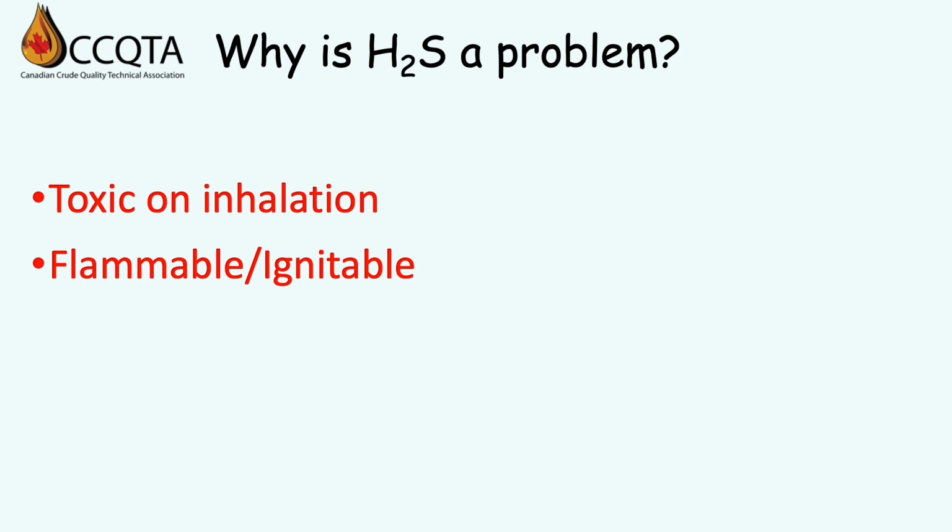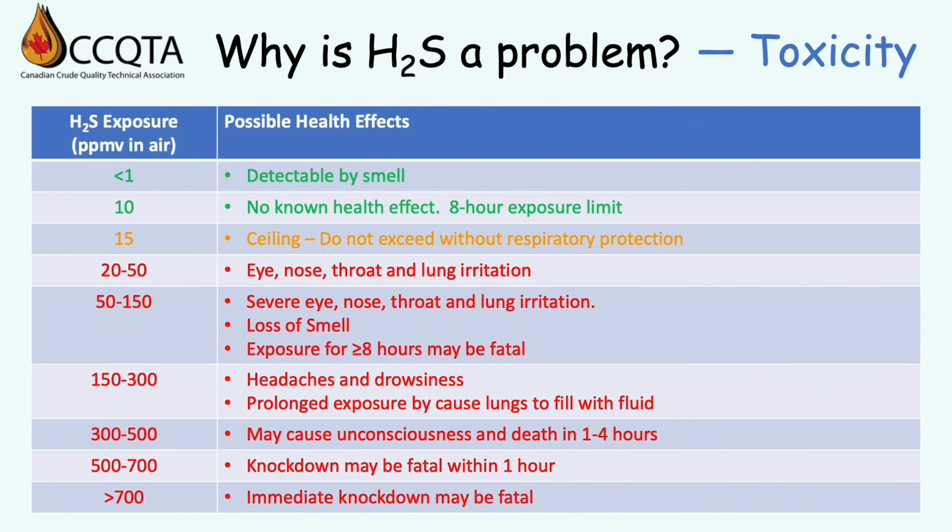First, let's talk about the toxicity on inhalation. This table shows the impacts of H2S and highlights the time component of exposure. As you can see, with increasing exposure time, the severity also increases significantly. At 10 ppm, a person can work in that environment for up to 8 hours without any adverse effects.